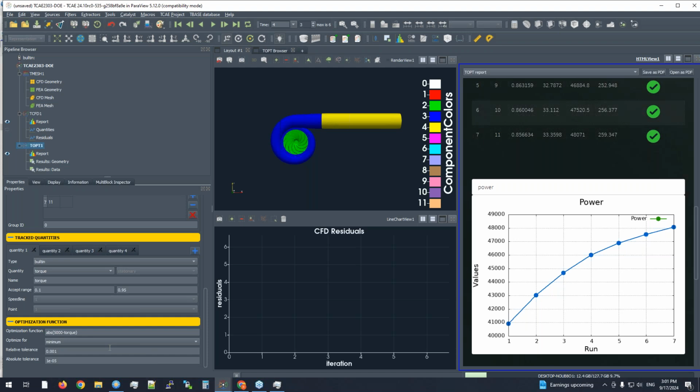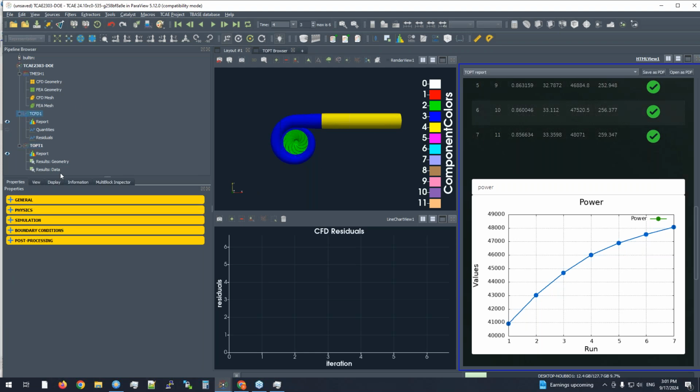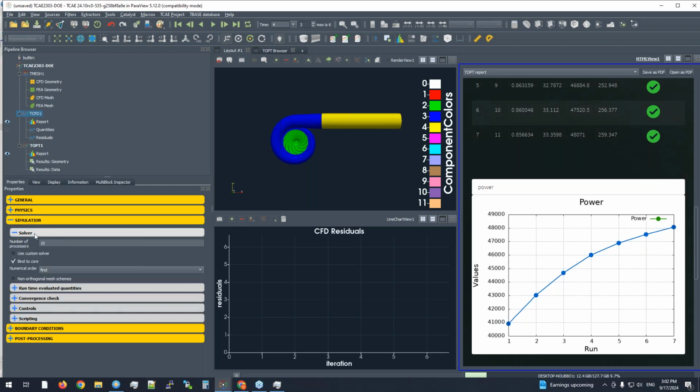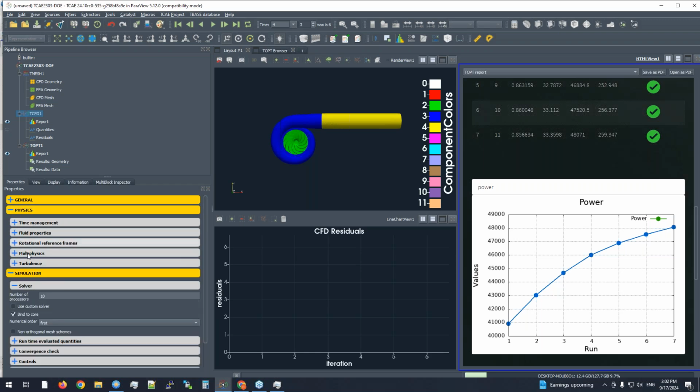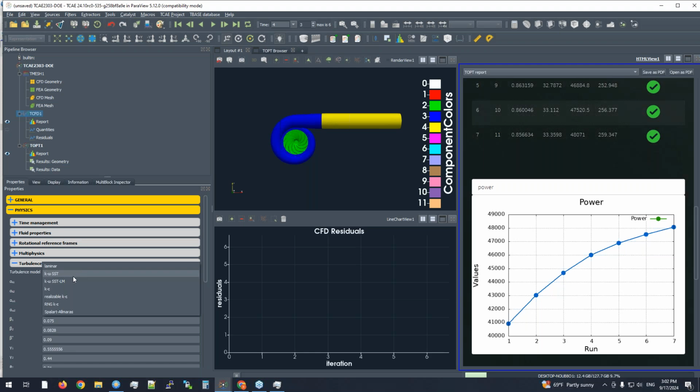Thank you. Welcome. The next question is, Ahmed is asking what turbulence models are used for the pump, or would you recommend one? Okay, so in general we use the K omega SST. If I go for the physics turbulence, K omega SST is a standard, but sometimes we also see that you can go for a realizable K epsilon, but it is always connected to the given application and to the experience with the model. But in 95% of cases, we typically stick with the K omega SST model. But it depends on the user and on the application, of course.